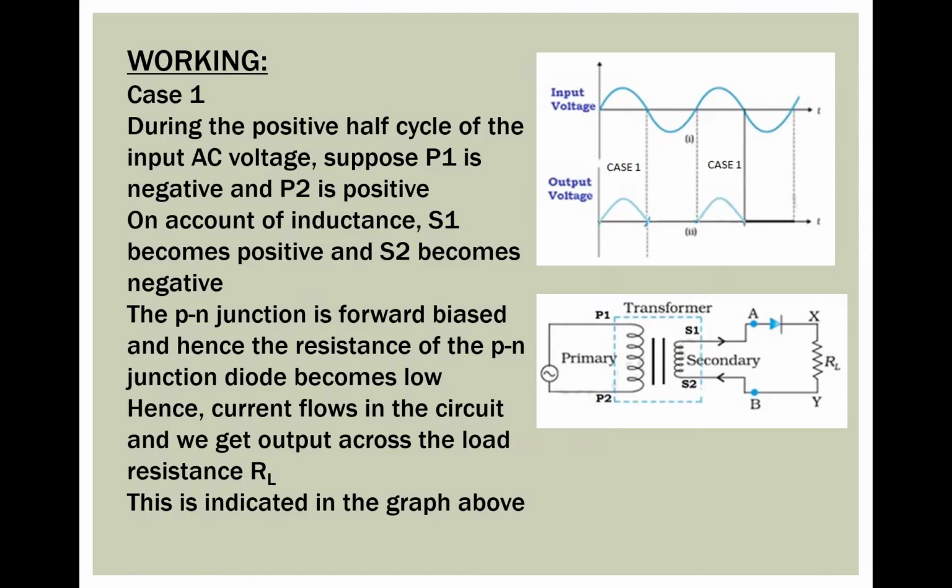For the negative half voltage, the diode acts as an off switch, so it doesn't allow any voltage to pass. No voltage will pass from the input to the output, so no voltage is present at the output. Coming to the next wave, again the positive half wave is presented in the operation. If you give the complete cycle as the input voltage, we get only the positive half voltage as the output voltage.